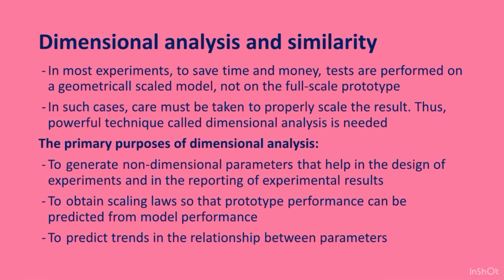The primary purposes of dimensional analysis are, first, to generate non-dimensional parameters that help in the design of experiments and in the reporting of experimental results. Second is to obtain scaling laws so that prototype performance can be predicted from model performance. And the third one is to predict trends in the relationships between parameters.